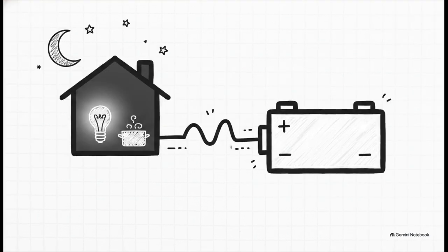To really ground this battery storage idea, let's look at a concrete real-world example. A standard 10 kilowatt-hour lithium-ion solar battery can power a typical house, say one using 5 kilowatts, for about 2 solid hours. This perfectly covers that super crucial evening window right after the sun goes down. You know, when everyone's cooking dinner and blasting the AC or turning on the lights, dramatically reducing your reliance on the grid when electricity is usually the most expensive.